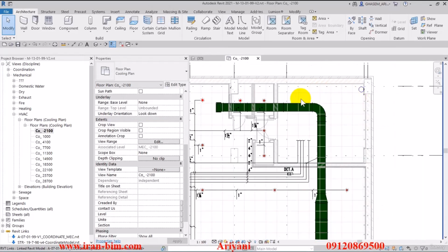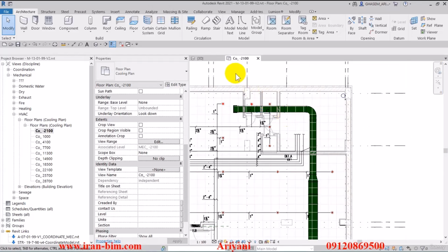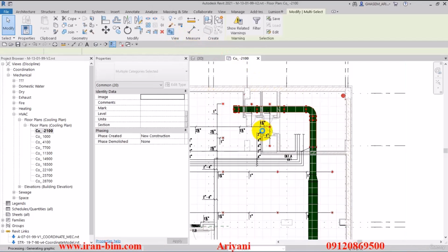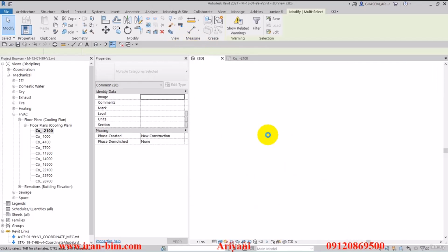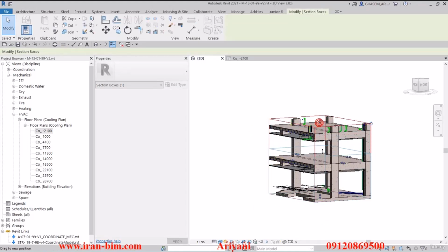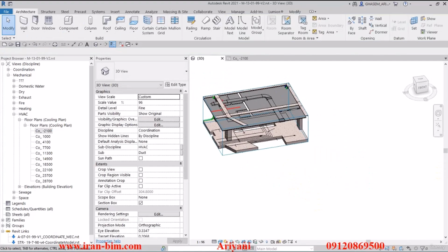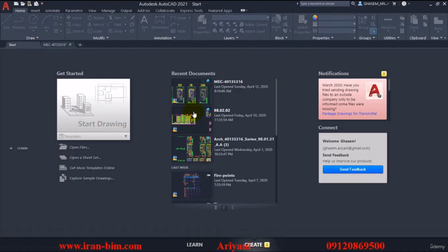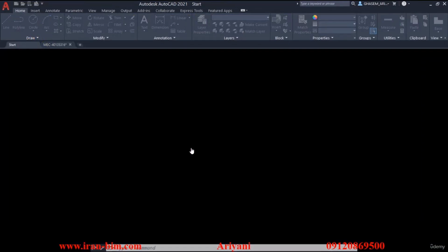And the part associated with the changes is supposed to be here on the right. So now we can see a duct go through here, which is a bug. So I'll select this bit and then I'll hit a section box. And this is a great case of how much modeling can help performance. Now I'll bring this down, and another important point that we have is, well, let's see if the mistake was on our part or was it the architectural plan.